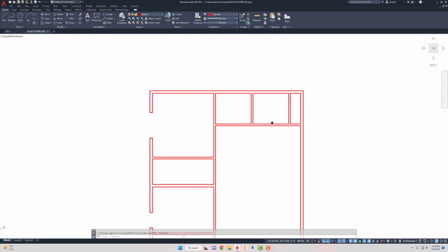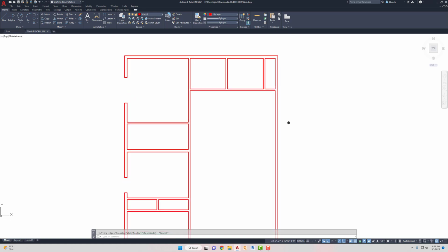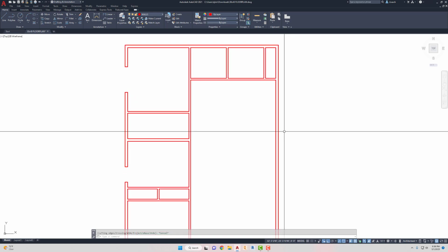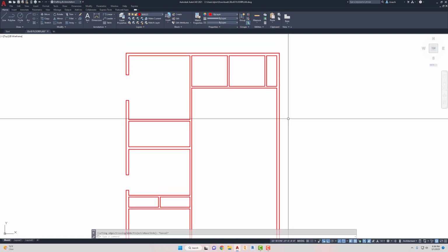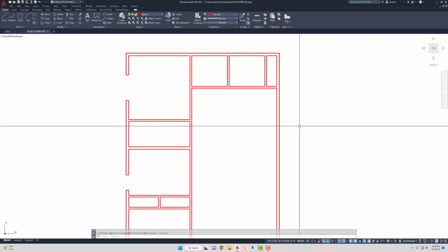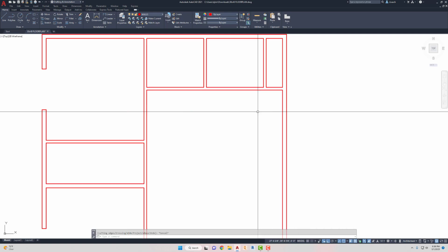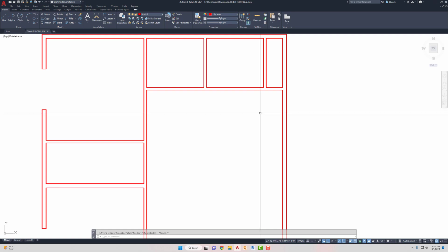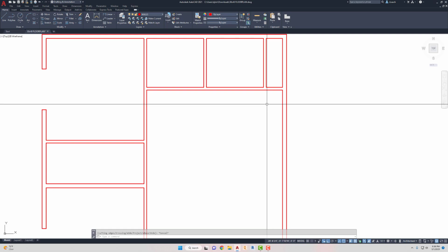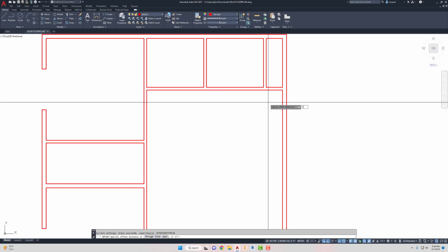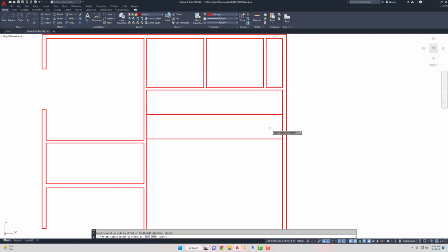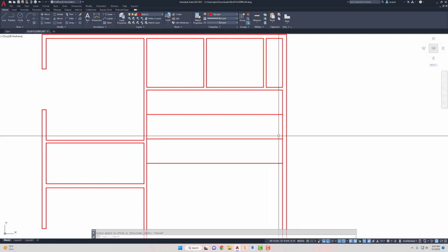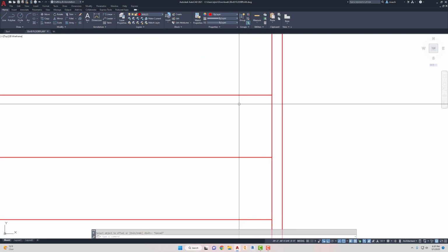All right, moving along. Now I got 3 windows over here. There's one that's going to be right over where the kitchen sink is. So that's probably going to be about a 3 feet wide window. So I'm going to try to assume where this would be. Your cabinets, usually they come in, what, 3-inch increments? So I'm just going to say that I'm going to offset 36 for that row, 36 here, 36 here. So I'm going to assume that the sink is going to go right in here.